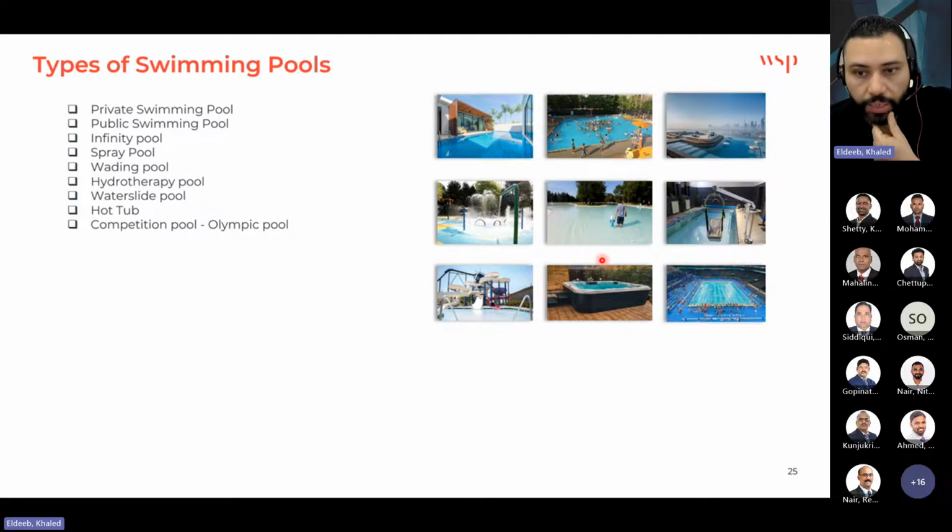In general, no specific shape or dimension is required for pools. The shape is designed for its own purpose based on the architecture or landscape design perspective. For example, regarding the swimming pool size, the designers, the architect or landscape designer, usually size it like this: if we have a shallow pool, they consider 1.4 square meter for every person.